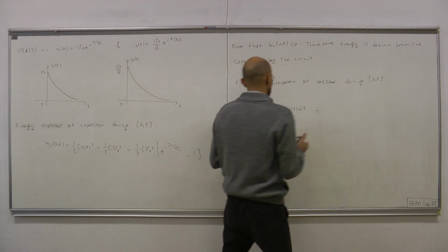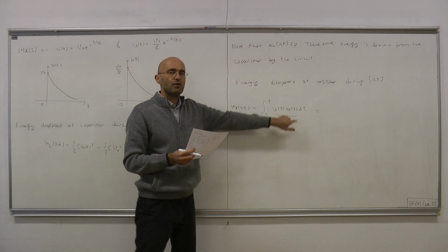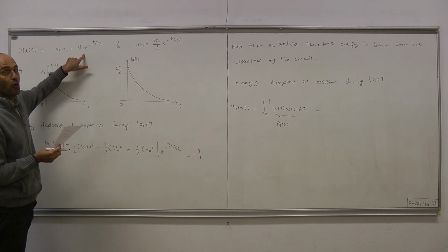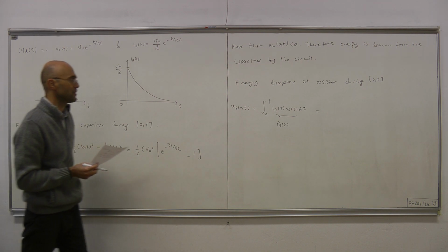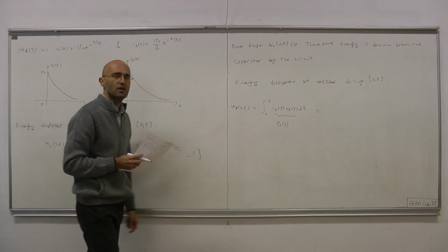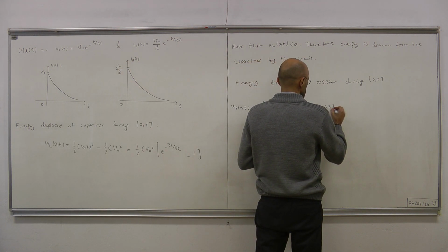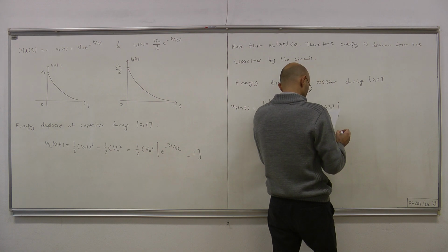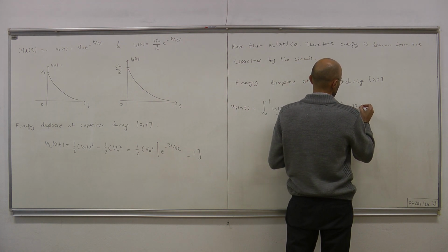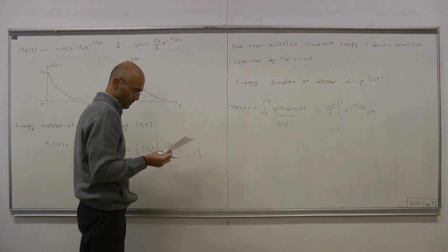Now that equals, we know IR of t, and that's for VR of t, because R and C are in parallel, we also know that it's V0 e to the minus t over RC. Therefore, we know both terms, that means we know the power, and we can compute the integral. So that equals V0 squared over R, integral from 0 to t of e to the minus 2 tau over RC d tau.